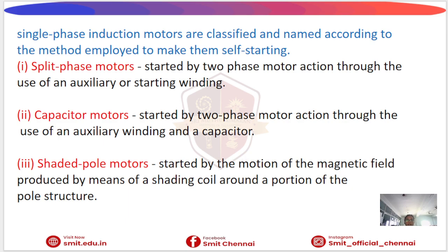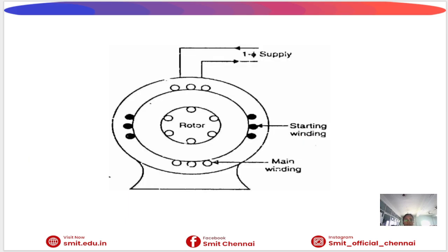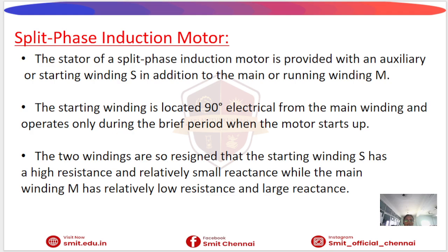Design of windings. The two windings are designed differently. The starting winding has higher resistance and low reactance. The main winding has low resistance and high reactance. This design helps in creating a phase difference between the currents.